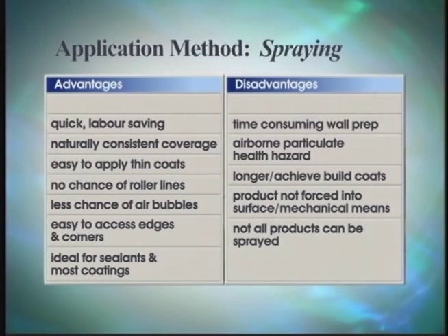Application method: Spraying. Advantages: Quick, labor-saving during application. Naturally consistent coverage. Easy to apply thin coats. No chance of roller lines. Less chance of air bubbles due to thinner coats. Easy to access edges and corners. Ideal for sealants and most coatings.